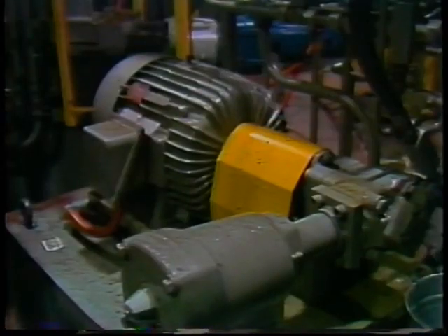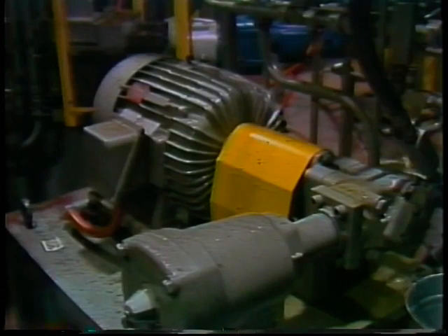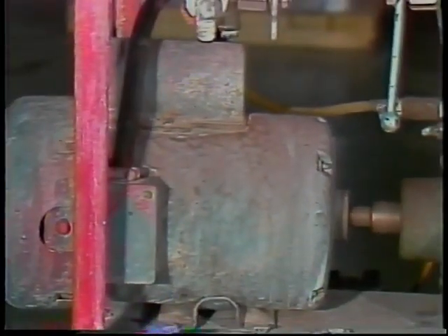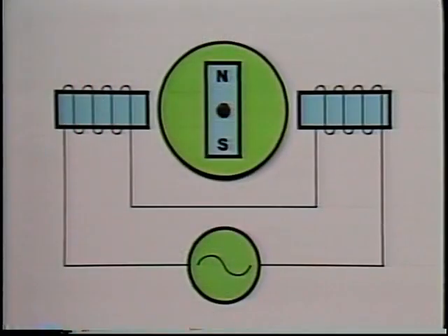So far, we've been looking at three-phase AC motors. We have seen how induction motors start up and run on three-phase power, and why a synchronous motor needs to start as an induction motor. When the AC is single-phase instead of three-phase, even induction motors cannot start themselves without special provisions. The problem is that with single-phase power, the stator poles alternate back and forth but do not actually rotate around the motor in a definite direction.